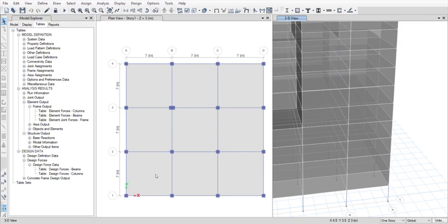From there, if I calculate the column strip width, that is 0.25 times L1 and L2. As you can see, both L1 and L2 are 21 meters. So when I multiply by 0.25, I get 5.25 meters. That is the column strip width. As there is no concrete provision for strip width, I can choose 5 meters.